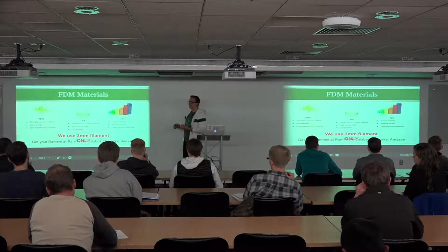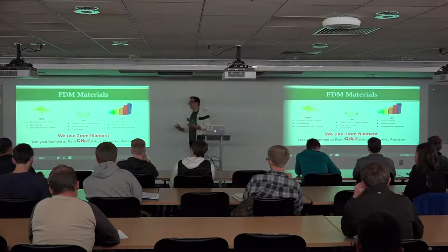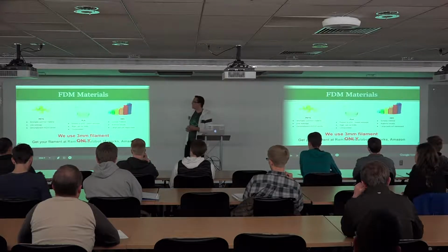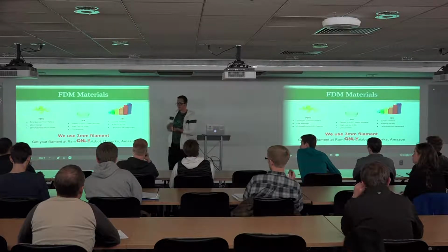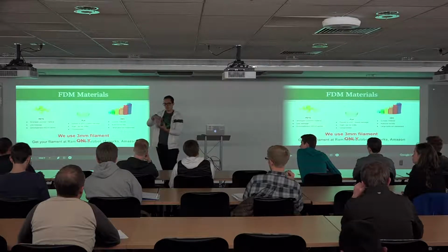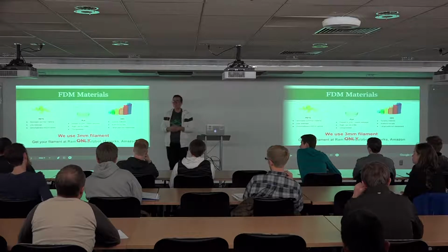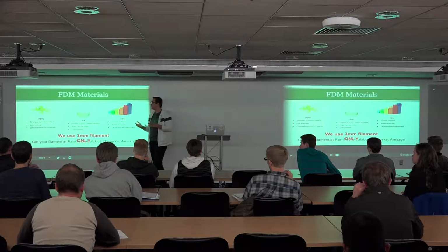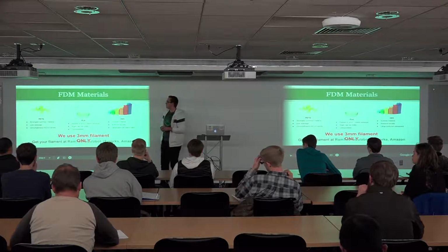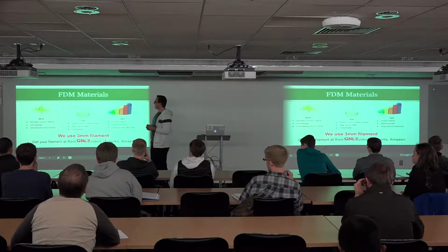It's a strong material. It's similar to what your Nalgene water bottle is made out of. I can't say it's food safe because nothing 3D printed is actually food safe. It will be FDA certified, but once you 3D print with it, you've got about a billion different spots in between your layers where bacteria can and will grow. It's one of those things where you could probably print something and use it once or twice, but it would be a little messy to use it more than that.